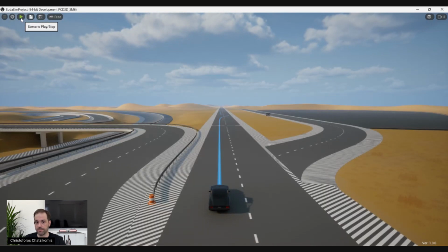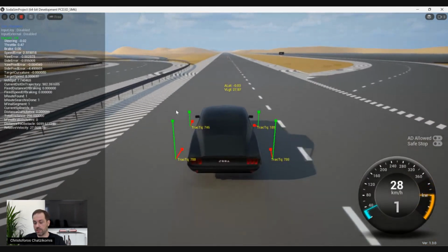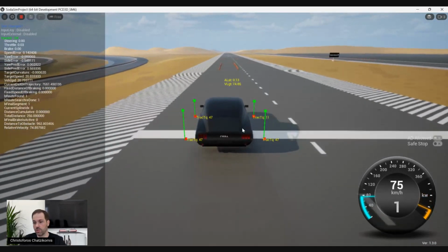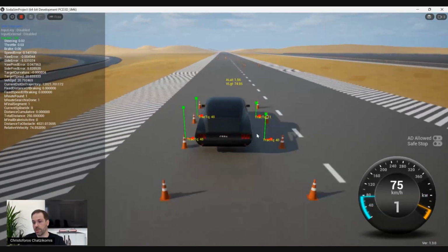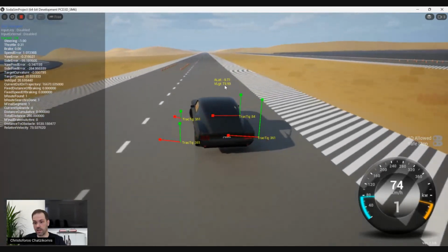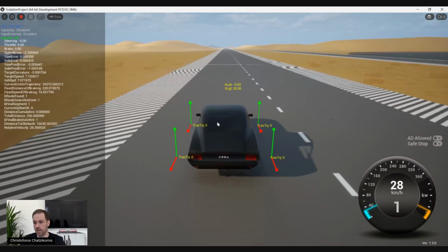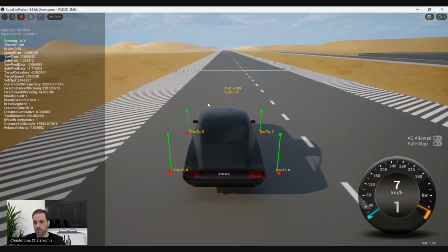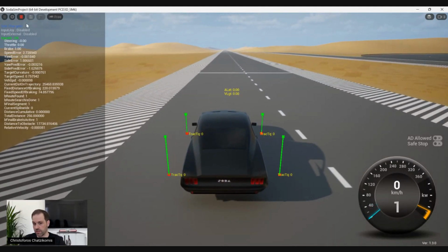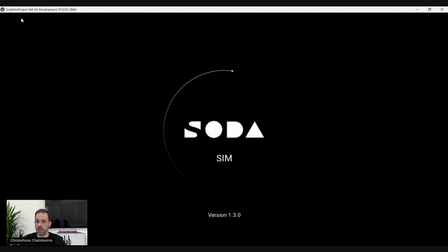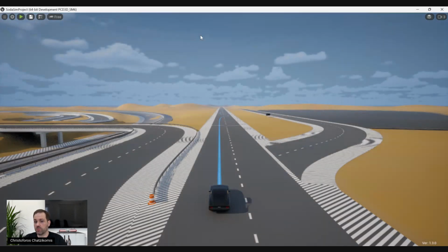a scenario like this. So now we get the visualization for the tire forces, the vertical forces, the longitudinal forces. And we will see during the maneuver, for example, that we have these lateral forces and the lateral acceleration that goes, for example, up to 9 to 10 meters per second square, which is what we would expect from this type of vehicle. So we see now that by default, and at this speed, our vehicle completes the maneuver, but